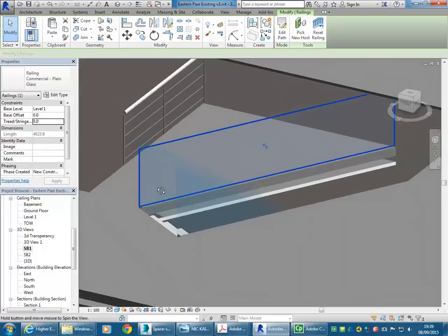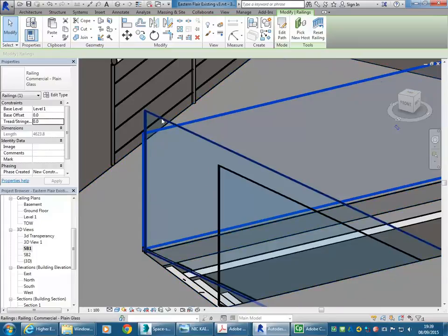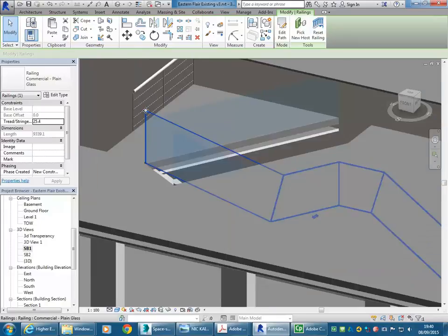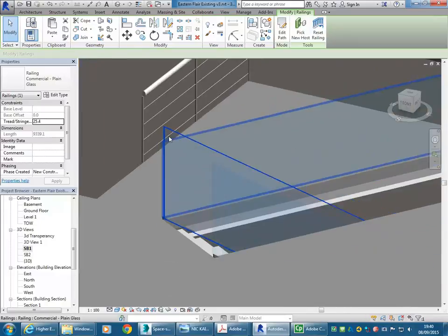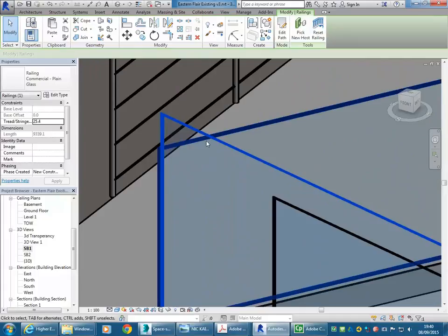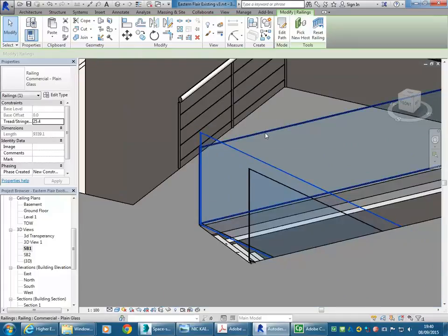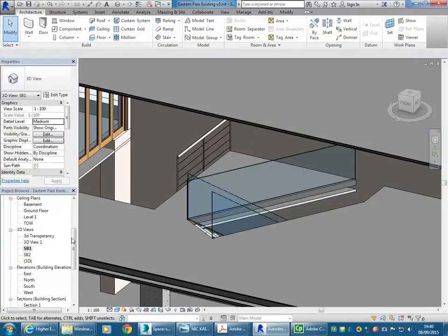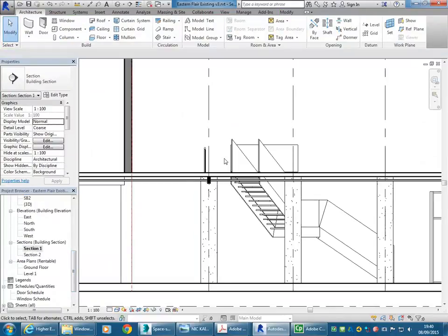And again, then you can see why there's a reason that they allow that lower height for stairs. Right, it's because when you're projecting from the stringer or from the angle of the stairs, you do end up with that higher panel for the top rail. It's always been a problem, but I think a better solution than trying to bring the railing for the stair down, why not bring the other balustrade up? Sometimes it's better to do that. Right, exactly, that's right, a lot safer.